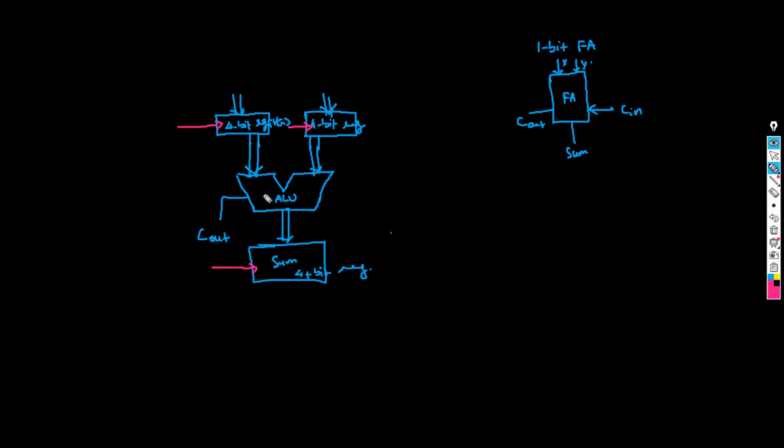Then you pass the data, because when the ALU is actually doing its operation, it could be your addition, subtraction, or whatever it is. If the input is continuously changing, it would give you wrong values. So we add registers before the data goes to the ALU, and then after the operation again there would be outputs that are maintained. Okay. So in this case, say it is a 4-bit ALU. Now there would be registers.